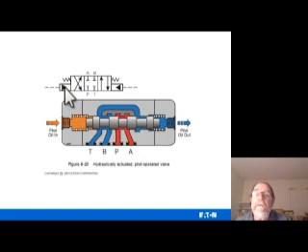And again, this is a pilot type. Okay, it's hydraulic fluid because the little arrow is painted dark. If there's pressure on these pilots, it will activate this. If there's fluid on this left side connection, it will move the spool to the right and make it where you're crisscrossed.